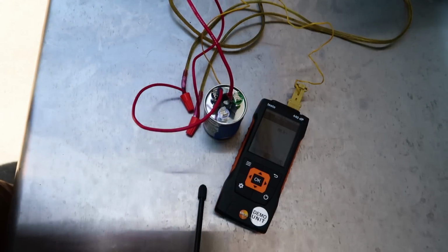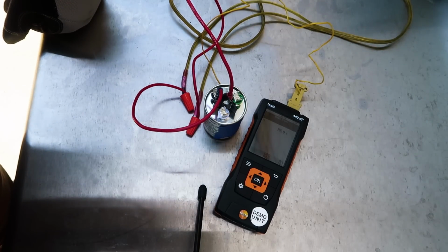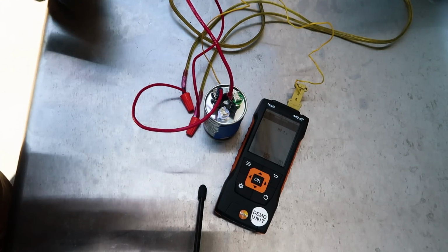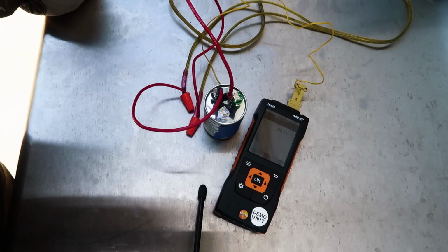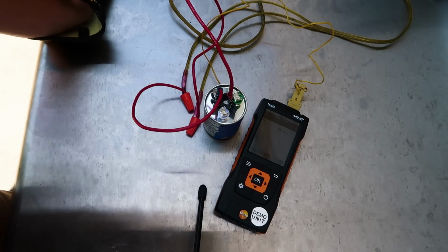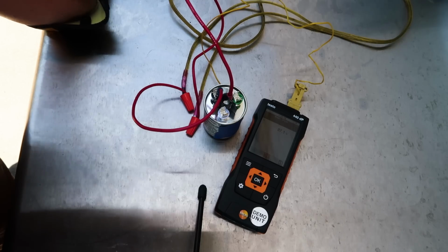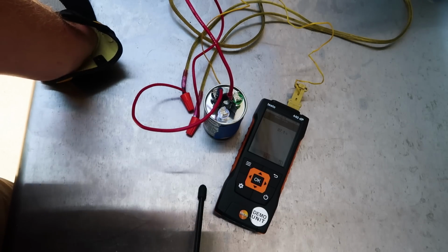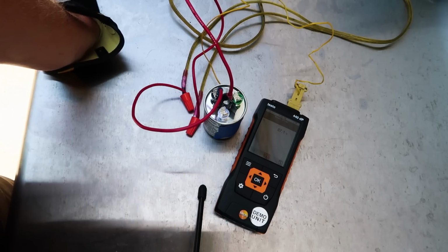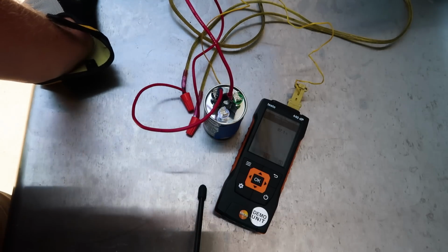Now the reason why these capacitors have metal shells is they have oil inside of them, and that oil helps keep them cool as those electrons are passing in and out. Because there is some heat generated as those electrons are moving in and out of the capacitor, and because it's always in the circuit, it never comes out, it doesn't have a relay that takes it out, it needs to have something to keep it cool. Over time it will slowly increase in temperature, but with the oil fill and the amount of load that I'm applying on it right now, it's not going to increase any significant amount. I've actually tested some of these before. Obviously it's going to increase in temperature because the outside is warmer than 87.